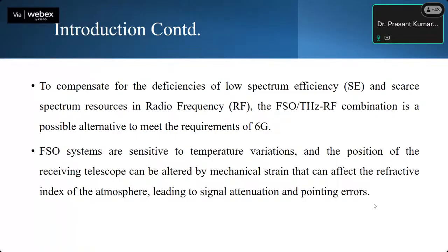So whenever somebody wants to design FSO for 5G or for next generation communications, there are some points that need to be considered. One is reachability, the dynamic adjustment of the range over which the signal can be easily transceived. That is the first thing. The second thing is how do we address the pointing error problems. People use a system called APT, whereby acquisition, tracking, and pointing are involved. But if you try to implement this APT system, it is very complex to deploy.